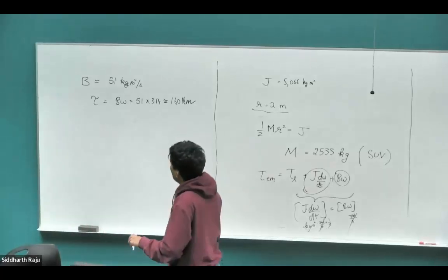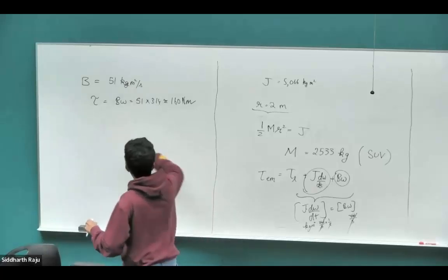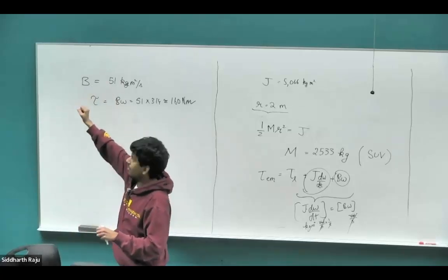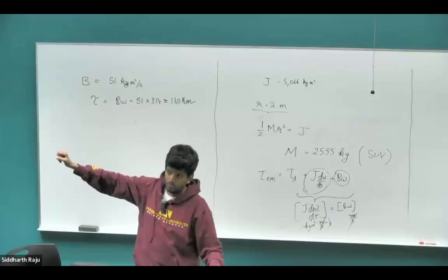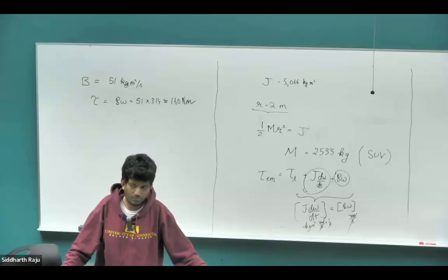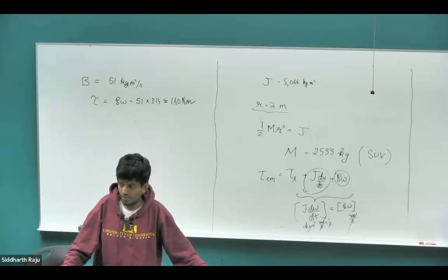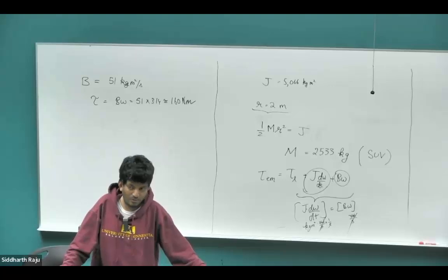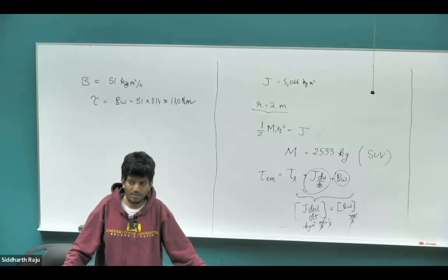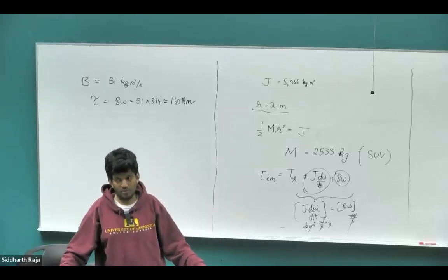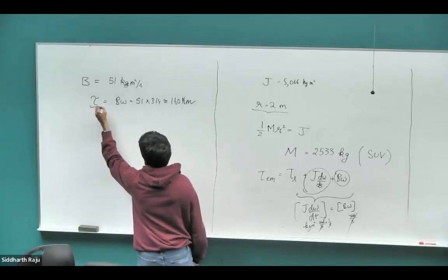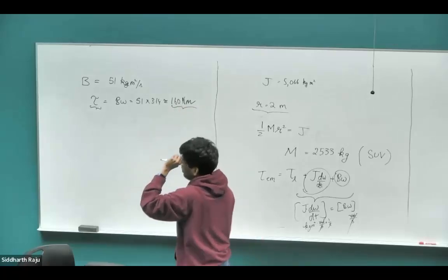Right? So the data sheet for this motor that was available on the website does not actually give this damping coefficient at all. So how do you think I figured out what the damping coefficient is to use for this particular example? Those of you who worked with motors, ordered motors, what value does a typical motor data sheet provide? We did see the case of the rating for the Tesla motor, right? So they provide the torque. So the torque value was provided in the data sheet as 160 Newton meter.